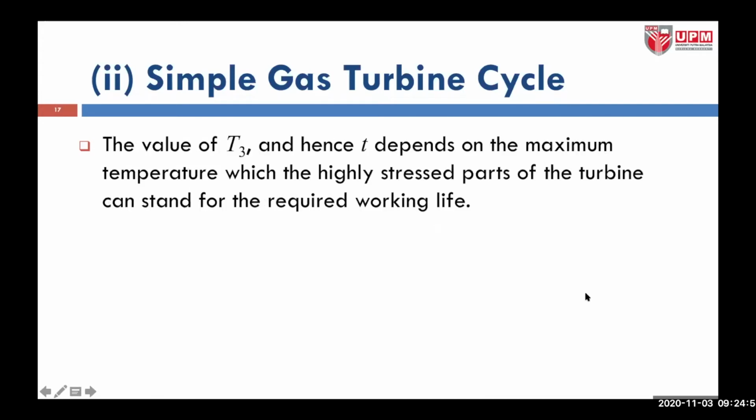And to continue, the value of T3, the turbine inlet temperature, and hence the temperature ratio, depends on the maximum temperature which the highly stressed part, which is the turbine, can stand for the required working life. We talked about this in general last week: the different materials and different cooling techniques on the turbine affect the performance or the temperature that it can withstand.